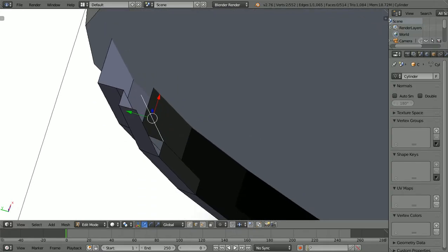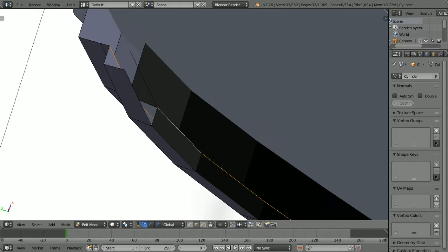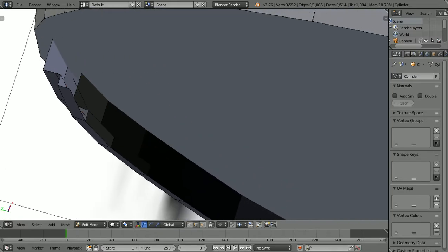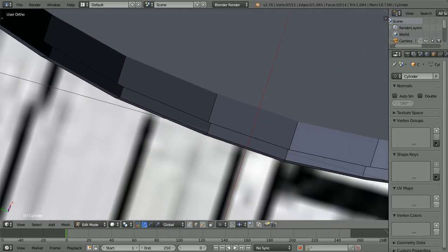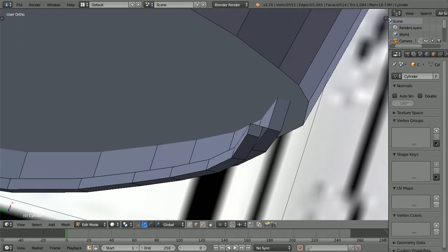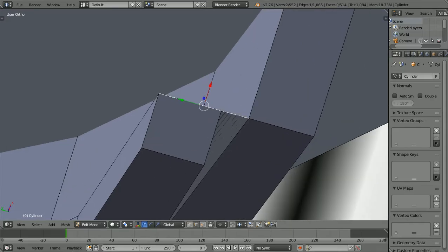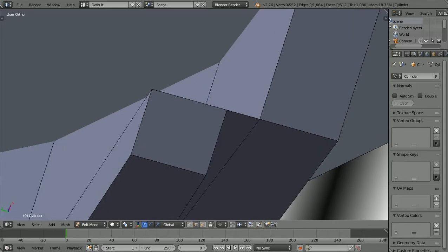Okay, so on this, what I can do actually, deselect it. What I can actually do is hit, I think, push Alt. No, that didn't work. Oh, I know why it didn't work. If we go to our other side here, it's looped, and that's why it picked the inside and the outside, but I just want the outside. So if I actually pick this one and delete it, because we actually have some double vertices here too, and I don't want the double verts if we can avoid them, and we're going to do a vert check here pretty soon.